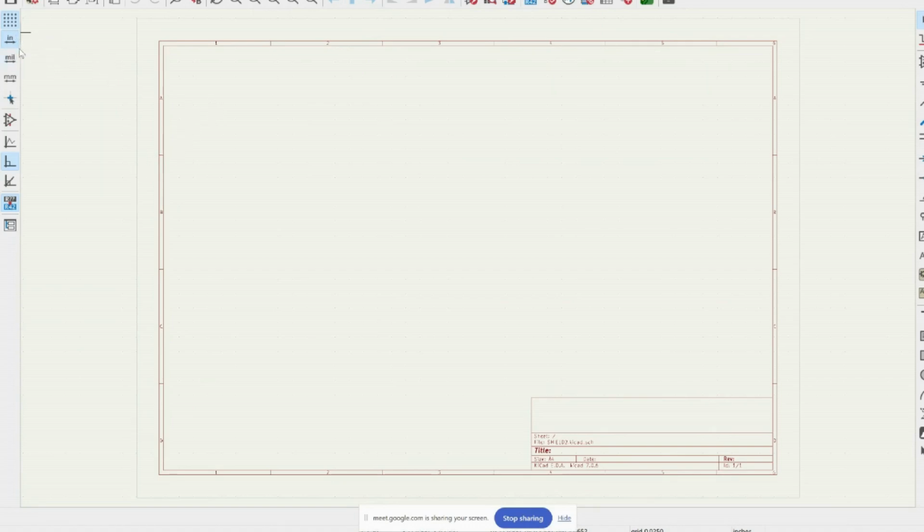One thing that I immediately notice about KiCad that is a lot different from other PCB design tools is that it puts on the front page something that always in other programs you got to dig down deep to find. And that is, what is the grid? So the grid is what basically, if you draw a wire, it will snap to that grid. In other tools, you have to dive through menus to find the grid. This is just sitting right here on the top left, which is super convenient. Not necessarily in the schematic, but more in the PCB design phase. But I think it's cool about KiCad.